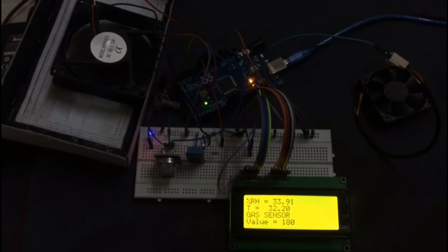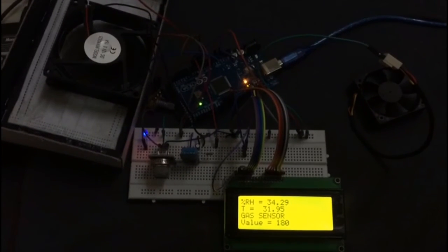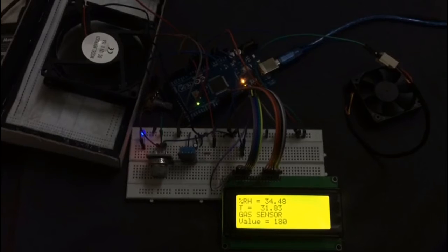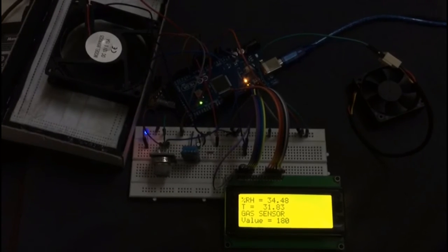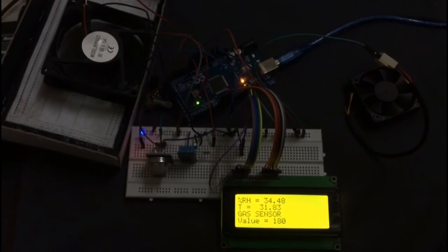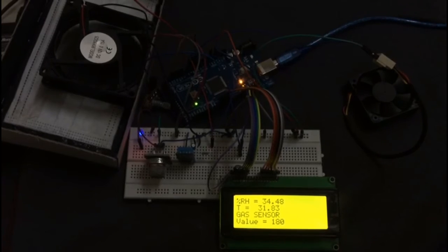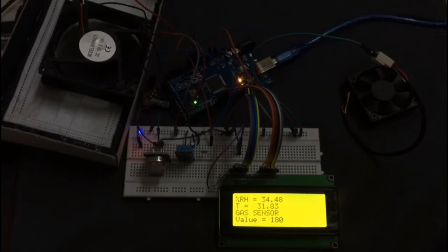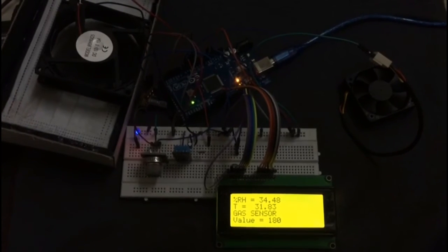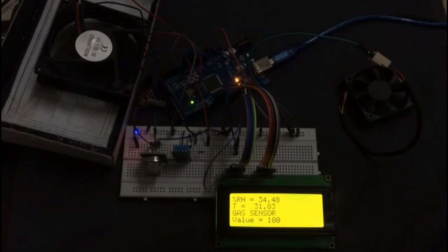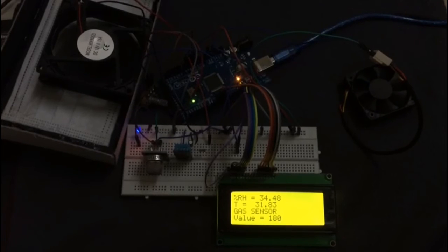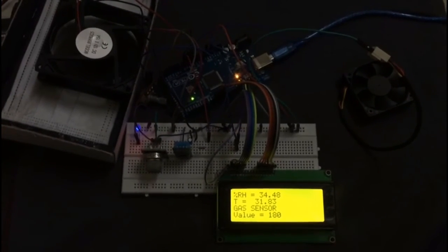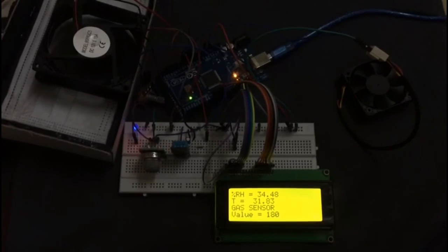As you can see, all the devices are working. The big fan indicates the air purifier, which will be turned on when the gas sensor reading is greater than 100. The blue LED indicates the dehumidifier, which will use the Peltier; the condition is greater than 30, and it will be turned on. The small fan indicates the humidifier, where the condition is less than 30, and it will be using Grove water atomization.